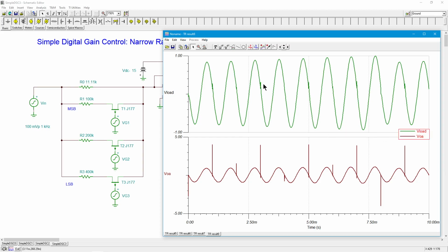All right, so there's still a little bit of the glitching here, where you got the really big spikes. You can still see there's a little bit of glitching, but it's nicely cleaned up. And in this version, you can also see the way the gain is increasing. It's going from a fairly modest gain over here, like I said, our gain of about 9. And then up here, we're getting a gain of about 11. But as I said, we're losing a little because of the lag network, so it never gets quite up to 11. We're only getting up to about 10. And then it recycles and starts at the low gain and works its way back up again.